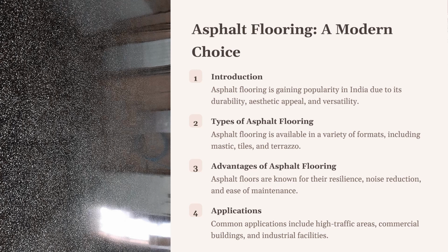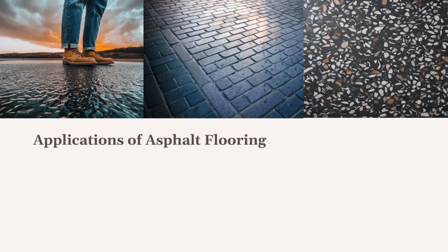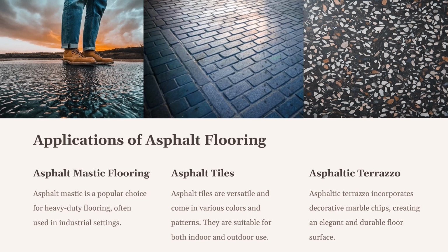This method is popular in high traffic areas due to its durability, often seen in shopping malls like the High Street Phoenix. Then there are asphalt tile floorings made from asphalt, asbestos fibers, inert materials and mineral pigments pressed into tiles ranging from 20 cm to 45 cm square with a thickness of 3 to 6 mm. These tiles, known for their resilience and soundproof qualities, can be seen in educational institutions like IIT Delhi, where both aesthetics and functionality matter.